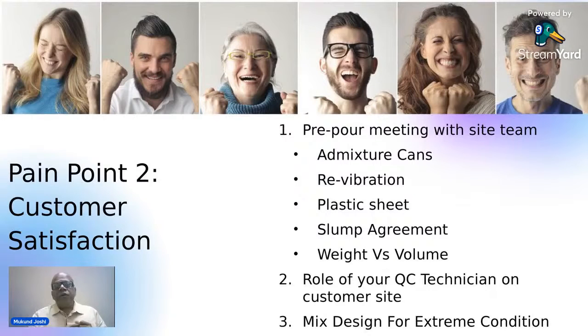There will be cracking on concrete, plastic shrinkage as well as drying shrinkage cracks because your water to cement ratio has gone up. So in a way, you are trying to hide one problem and you are exposing yourself to a big client dissatisfaction. Failure of cubes, I'm not even talking about that. I'm just talking about cracks which are visible immediately in first 12 hours to 36 hours. And we start losing client satisfaction from that point.